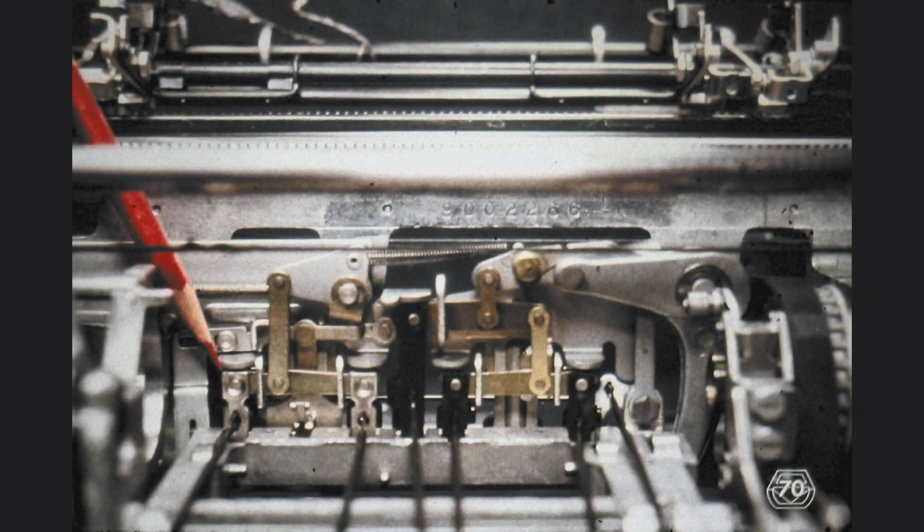If your reasoning went to the lever ratio, well done. The link to the tilt bell crank sits 2/3 of the lever's length from the pivot at the tilt 2 latch's stop pad, so the tilt 2 latch delivers 2/3 of the cam follower's motion, enough to swing the element from rest to the 3rd band of characters.